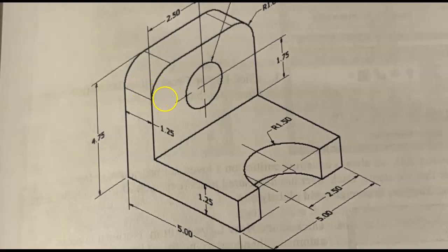So we are moving over now to create this L shape at the inclined angle. We see the distance, it's showing right here on our drawing, the distance of that leg or the thickness of the leg is 1.25. So enter that in, hit tab. This is going to be at 30 degrees. And hit enter. So now we're going to go back down, and you'll see it's wanting to auto snap.